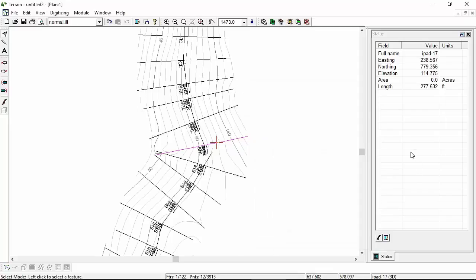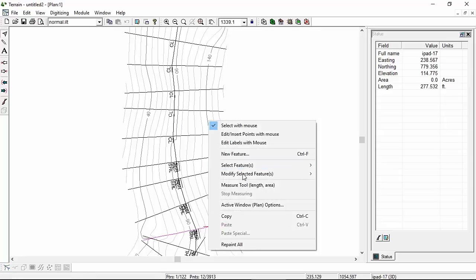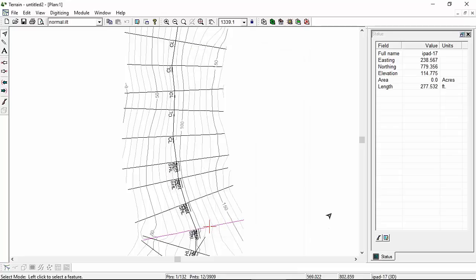There we go. There's my contours, and looks pretty good to me. It's just sloping down to the left. There's 140, there's 40, there's 90. Oh, why am I labeling like that? Let's just do that again. I don't want to label on 40-meter or 40-foot intervals, so I'm going to start my labels at 0. Oh, they're actually going below 0. Okay, so let's start at, I'm labeling every 50, so I'll start at -50. There we go. That's better. So there's 150, there's 50, there's 0.